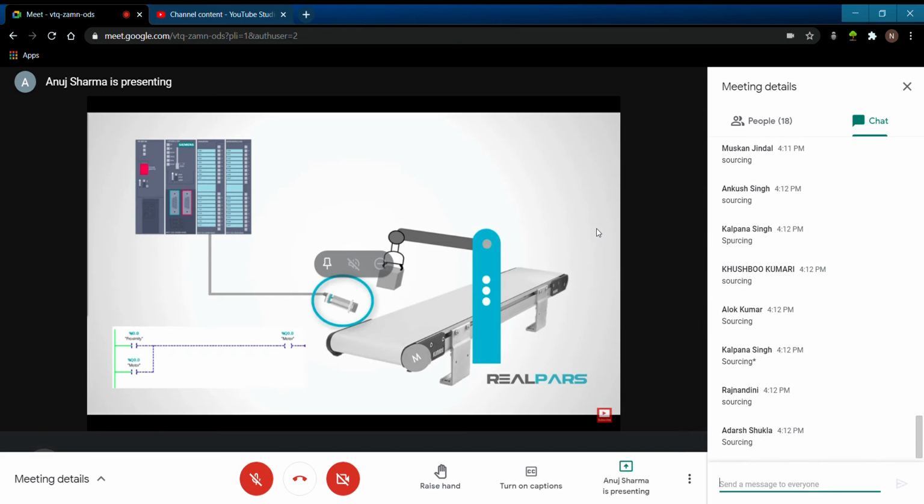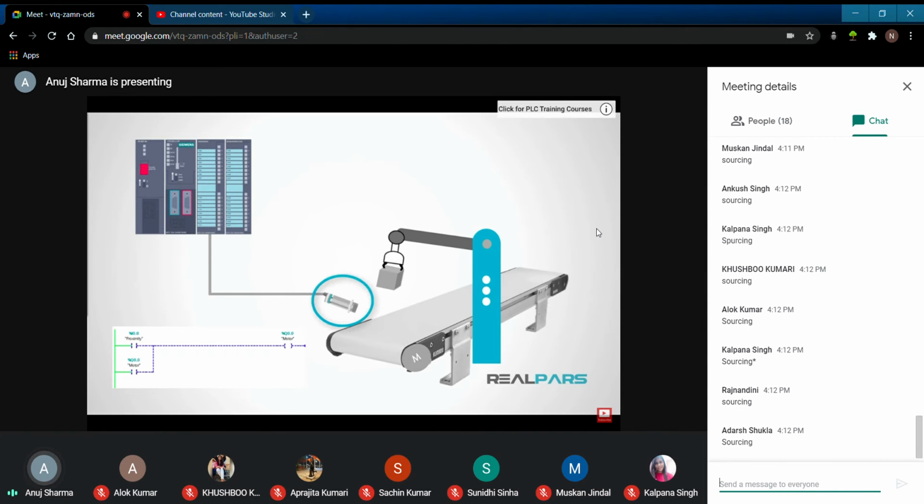The inductive proximity switch is connected to a PLC input card, and the logic program is written to sense the state of the switch. For instance, when a box is placed on a conveyor at the loading position, the proximity switch senses the presence of the box and commands the conveyor motor to start to transport the box to the next inspection station. So, let's see how we can make this important discrete sensor input information available to a PLC program. In order to do this, we need to understand more about these discrete sensors and how they are wired to the PLC.